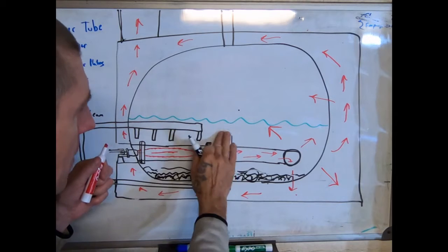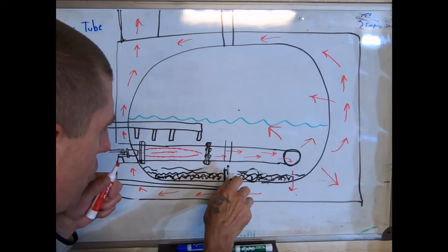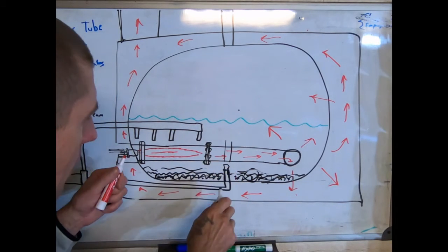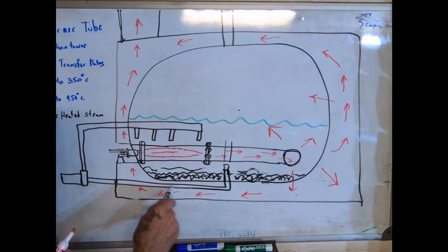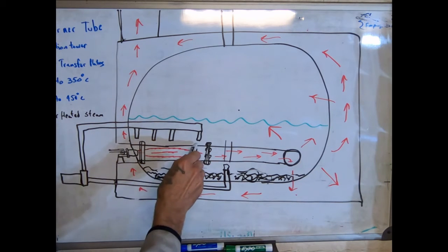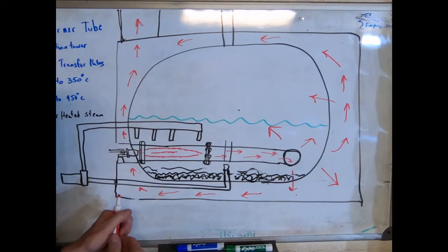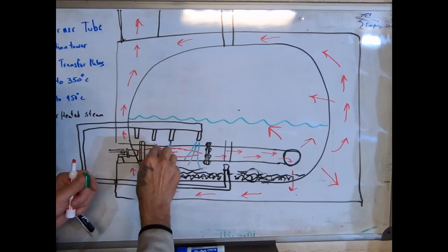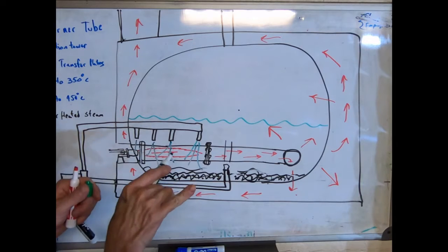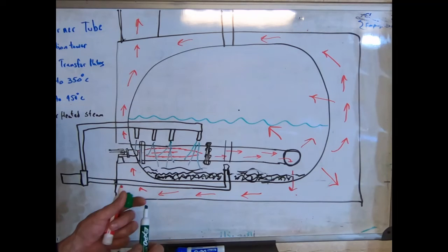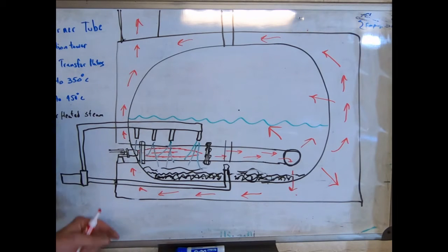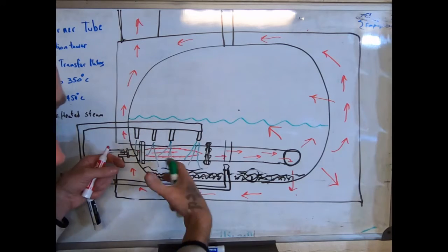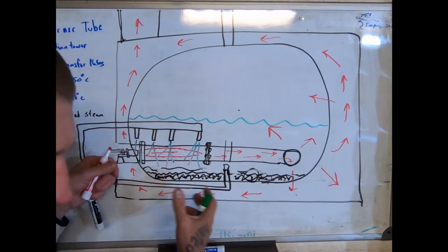I'd recommend that it be just below the heating tube, and that extracts fluid from the tank to a pump and throws it back out these rails and blasts this section of the pipe with high turbulent flow of fuel. And what that would do is reduce the buildup of any gum or varnishing that might take place.